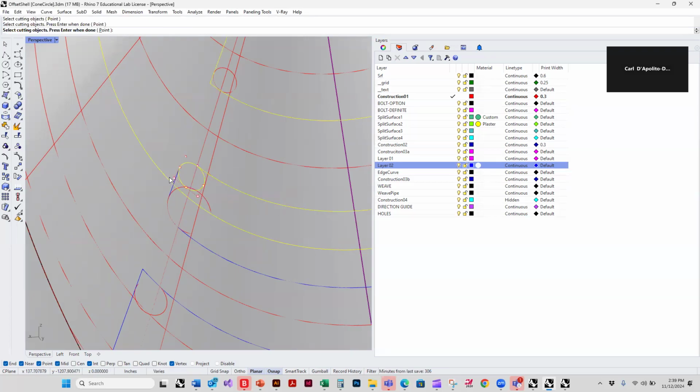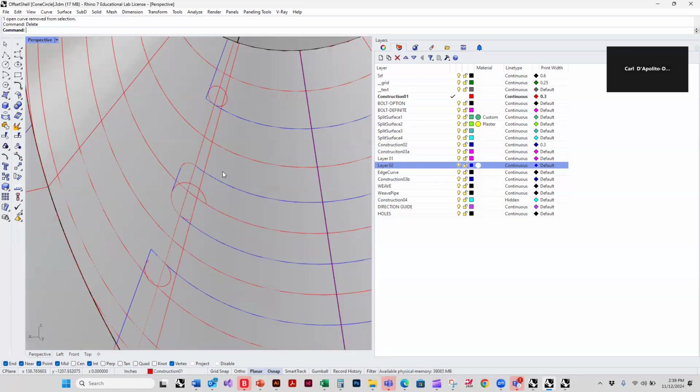Are they necessary to round the corners, or is this just an aesthetic thing? Well, it's necessary if you want the pieces to fit together because the router can't make a point. So the router will go here and then turn, and something will happen there that is hard to predict.